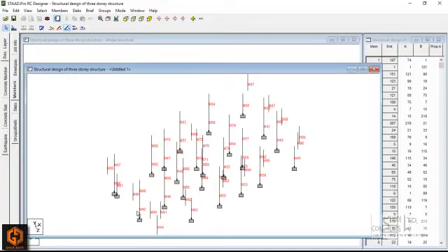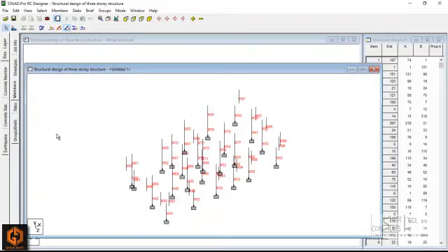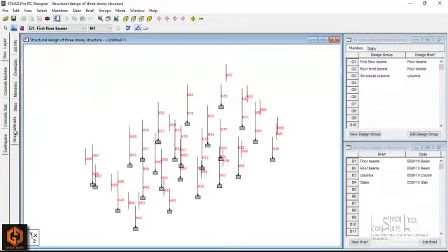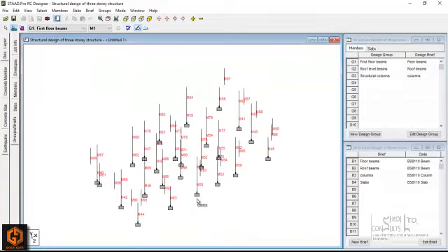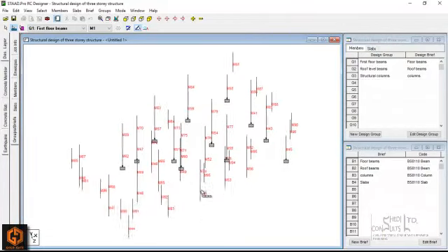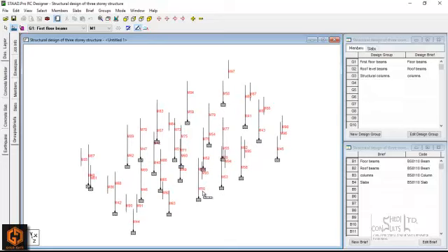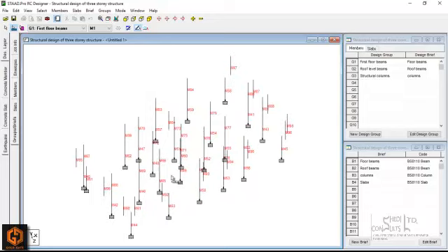As soon as you give your members their member numbers, you move to defining your design brief, just like a design basis. When you're doing a manual analysis, all your engineering design must have a basis of design. What are the bases you are considering? What are your design assumptions and so on? So you create a design brief.